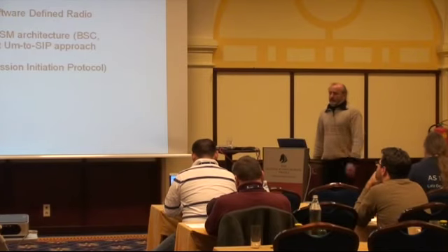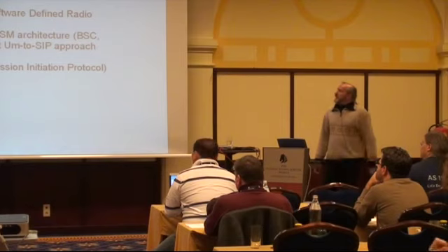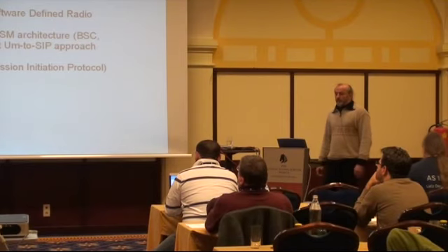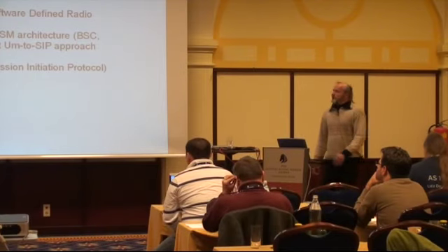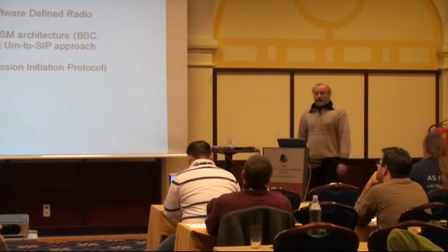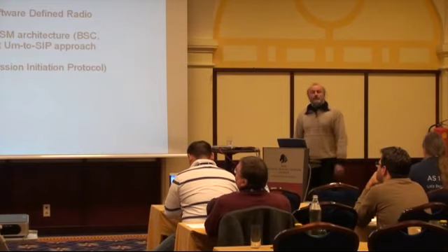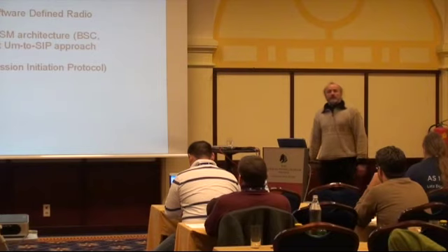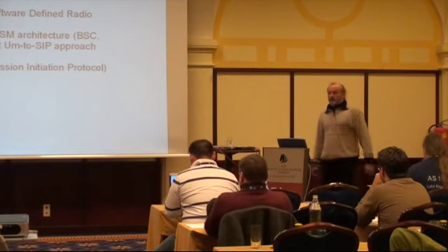Now a few more details about those open source projects. One of them is OpenBTS. As the name implies, it's about implementing the base transceiver station. The hardware of OpenBTS is based on the USRP, the Universal Software Radio Peripheral. This is open hardware. You get the diagrams, the schematics, which can be used to send and receive on a rather wide range of the spectrum, basically from DC up to several gigahertz.